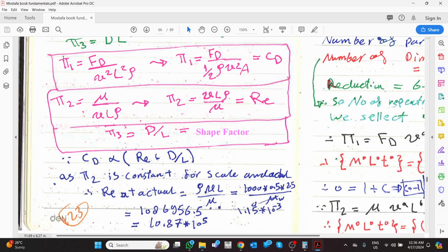So which is pi 1, pi 2, pi 3, whatever. This means when I do scaling, I need to ensure this one is constant and this one is constant and this one is constant, which is the physical similarity. This one appears like the Reynolds number, which is part from viscosity, and part kinematic and dynamic, and this one kinematic and dynamic. Okay, but the definition is that each pi should be equal to a constant.